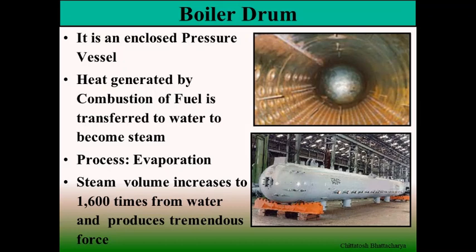So naturally, though it is placed outside the heat transfer zone and there is no heat addition, two-phase existence of the working fluid is there, but this is important for wetting of the water walls as well as for continuous supply of saturated dry steam to the superheaters, so that they are not starved of the cooling medium, steam.